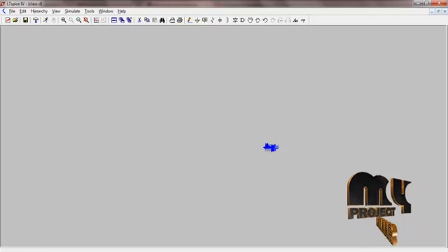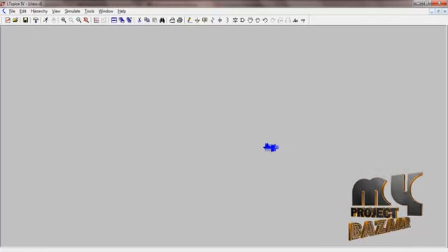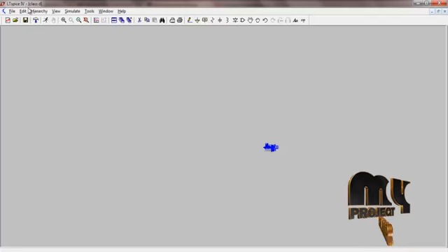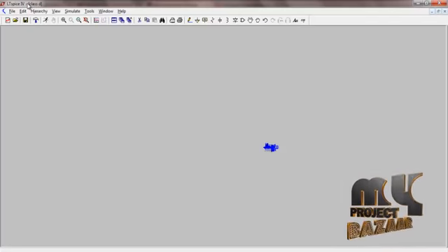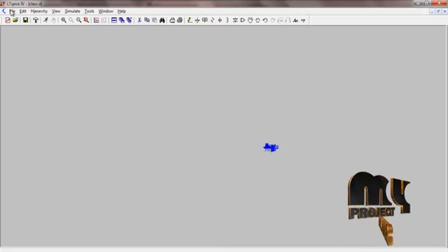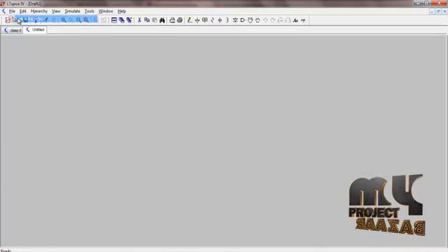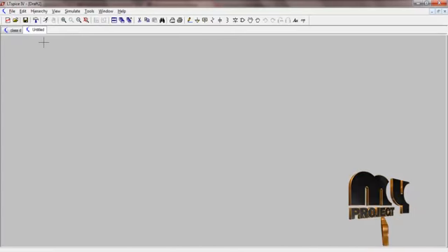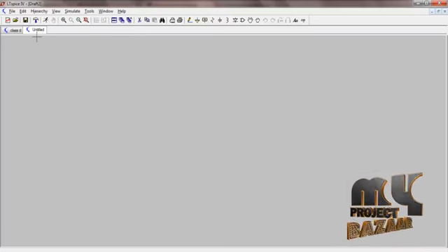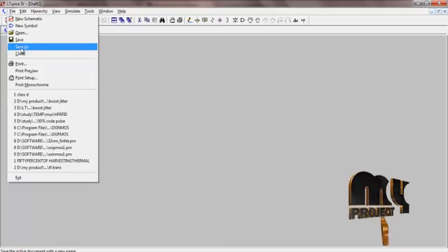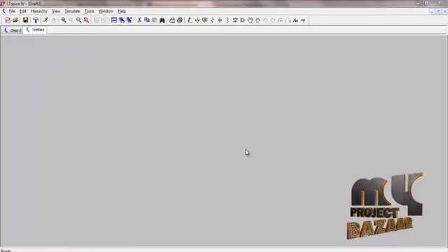Now we are going to discuss the running procedure of our product. In our product we are using the LTspice 4 tool to implement our product. First, we create a new schematic using the File option. Click File to create a new schematic. Our schematic will be untitled. In order to save this schematic, use the Save As option to save it with a desired name.